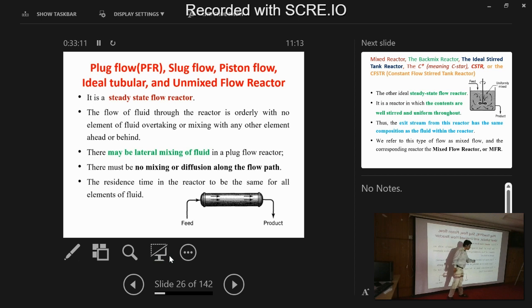Now, what is this lateral mixing? When I send the fluid here, look at the direction of the fluid. If it is a tube, the direction in which I send the fluid is called the axial direction, and the perpendicular direction is called the lateral direction. So for the plug flow reactor, there will be lateral mixing. That means along the axial direction there will not be any mixing, only in the lateral direction. The first top layer of fluid will mix with the next top layer. So lateral mixing is there, but not axial mixing.